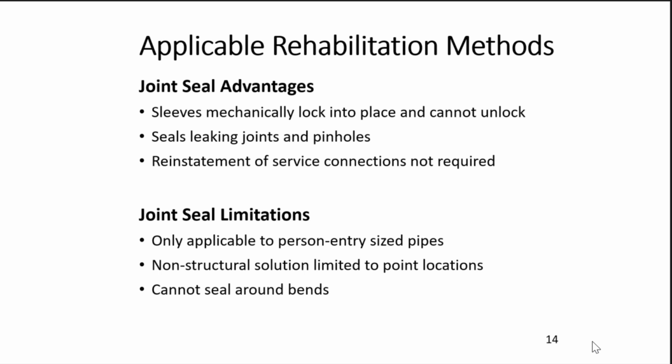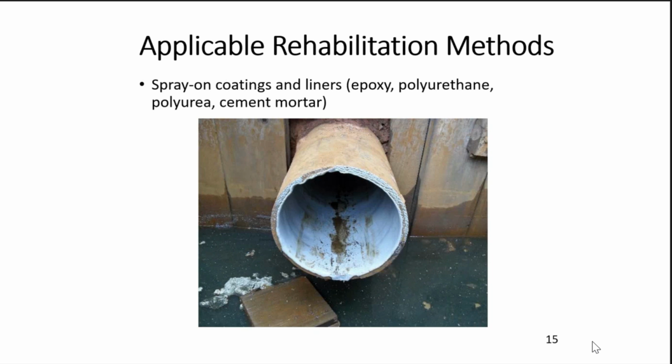But limitations, again, just person entry. For the most part, there's a couple little smaller ones that can go into smaller pipes now. But it's non-structural. It's not adding any additional strength to that pipe. The last one I'm going to talk about is one that we've done a lot of development and testing on over the years, and very recently in Deck as well, is spray-on coatings.